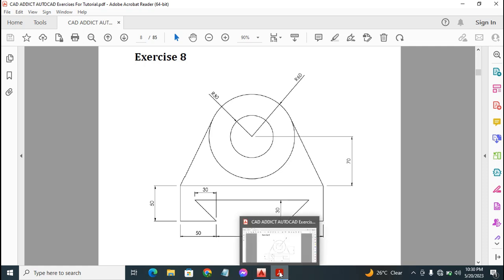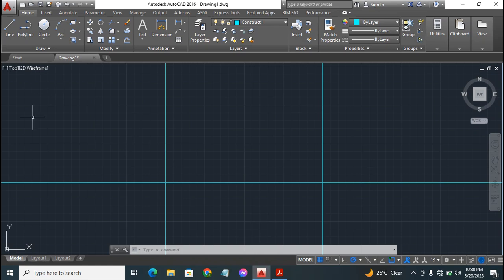So I'll go back to CAD. Alright, go to the draw ribbon, then click line, and I'll start from this point. I want my cursor to lock onto this point of intersection. As you can see, it's not doing that. So I'll go to the object snap down here at the bottom right of the screen. So I'll click on object snap.